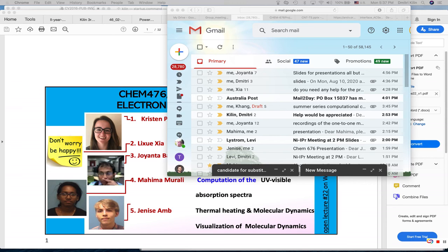In this KPOINTS file it is the Monkhorst-Pack grid, and the fourth is the number of subdivisions in each direction. This is the one we usually change to change the accuracy of the simulation calculation.